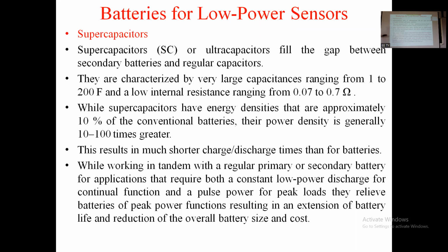Right? So see, this supercapacitor's capacitance is very high, or large. It ranges from about 1 to 200 farad, and its internal resistance is low, about 0.07 to 0.7 ohm.